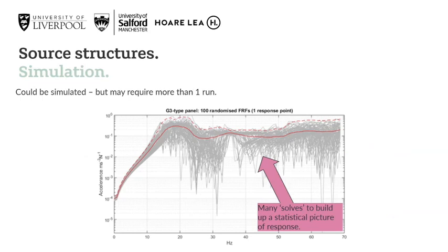And we were told before on webinar 1 when Carl made a reference to production lines, that even with the best production line, there will always be some slight variations in material properties and boundary conditions. And if we run a simulation, particularly a complex simulation that takes hours or days to run, that is a snapshot in time for a single set of material parameters. So for us to capture the real world variation, we may have to run a simulation a number of times to gain a statistical impression of what the actual response might be, or the variation in the response.